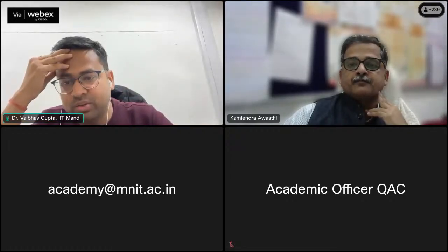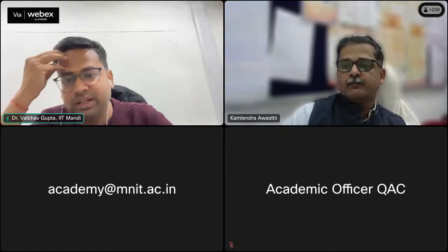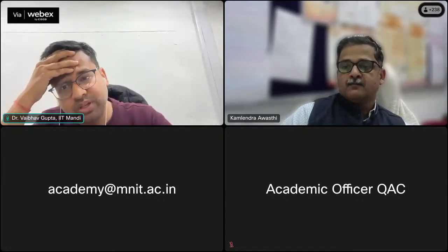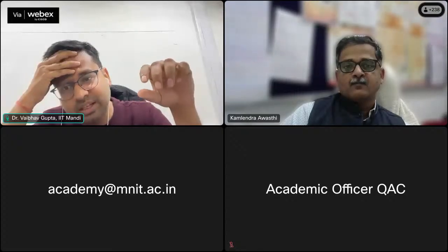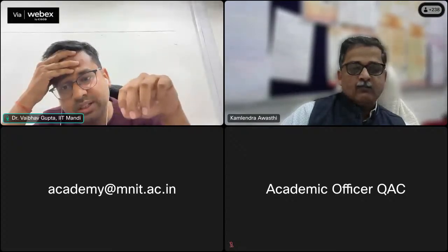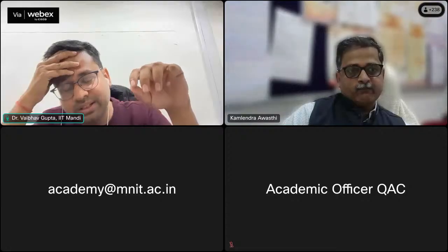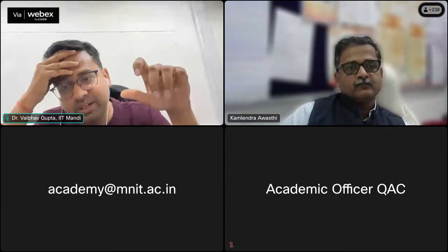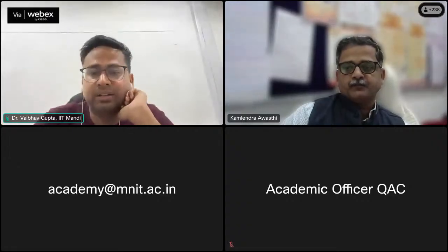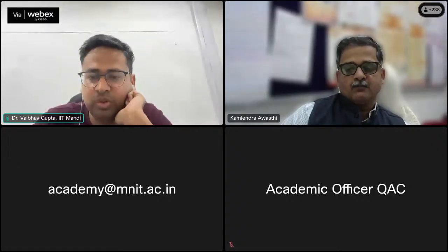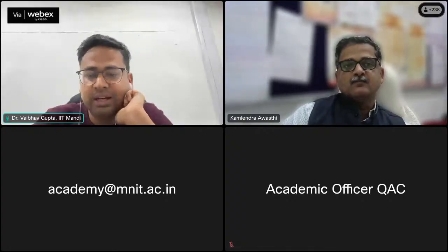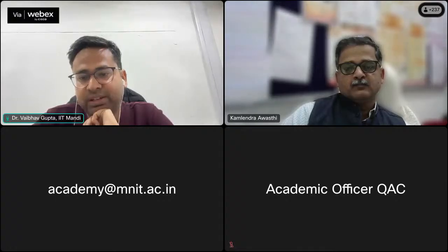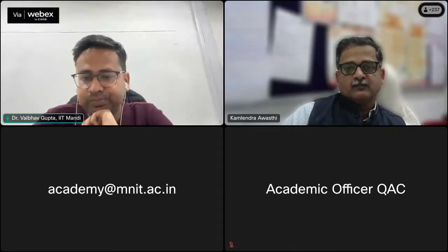Why is it called homodyne? So homodyne is detection. For example, in the last slide, what I showed you is that when we have the laser, we use the same laser to create the local oscillator. So when the frequencies or the wavelengths are the same, we call it homodyne detection, and if it is different, then we call it heterodyne detection. Typically, what we do is heterodyne detection, because in general, even if you use a beam splitter and use a laser, it is very difficult to create the same frequency or wavelength.